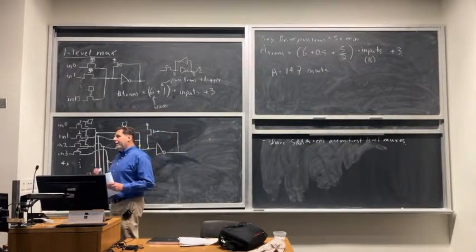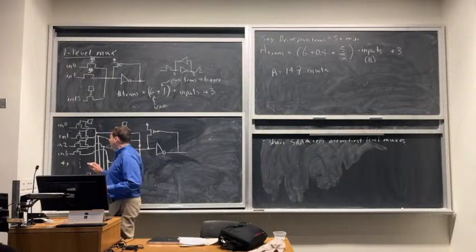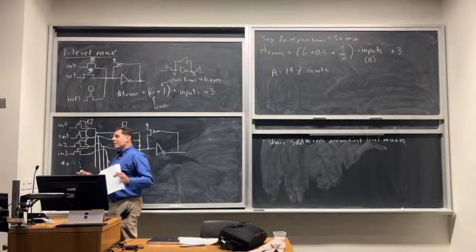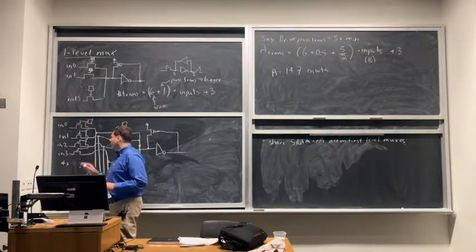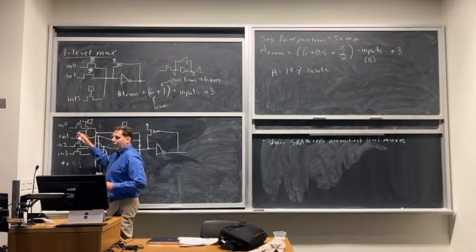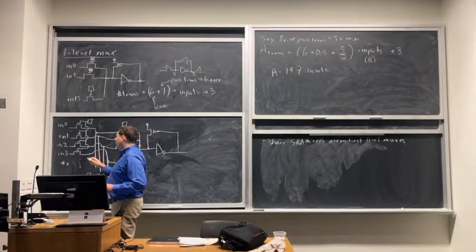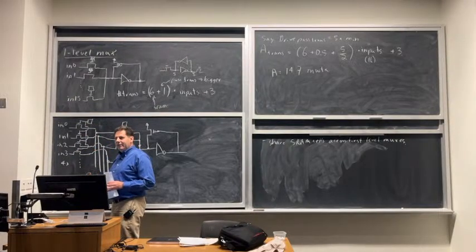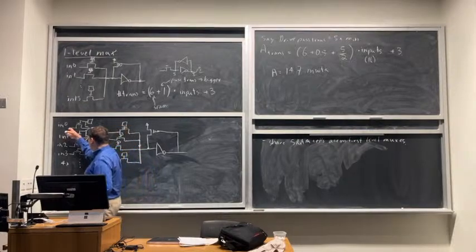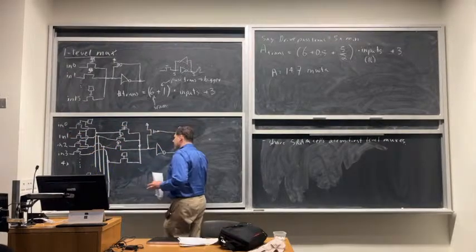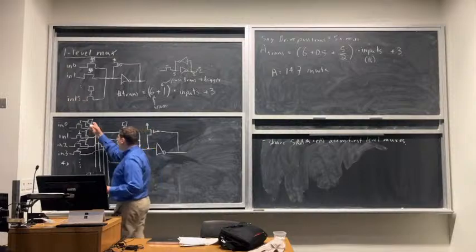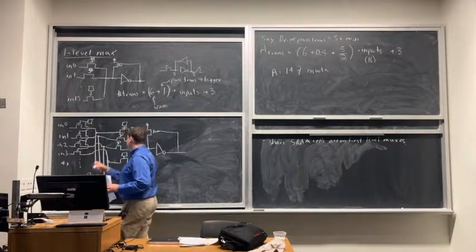After the router is done, a final tool called the assembler or programmer basically looks at what the placement did, what the routing did, etc., and it works out all the ones and zeros. So that tool has to understand how the mux is built. The programmer would say, okay, you want to go from input 0 to this LUT input, I need to put a 1 here and a 0 in these 3, and I need to put a 1 there.